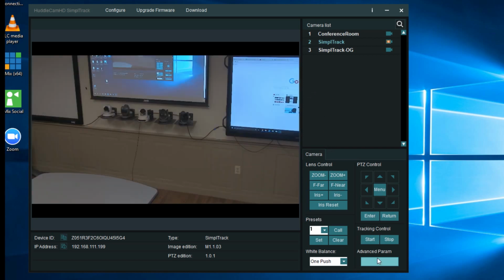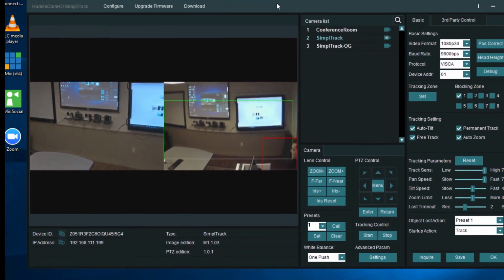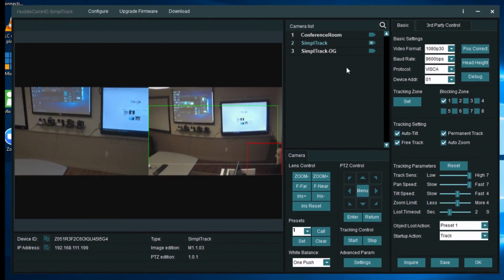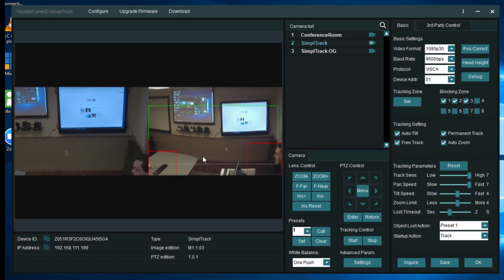If we hit the advanced parameters, there we go. We can set up 8 different blocking zones. So we put that one blocking zone there in the bottom right. But if we want to set up a second blocking zone, maybe in the bottom left, and then maybe even a third blocking zone, all the way across, that would allow us to protect that area. So if I were to walk in front of that area, it should...